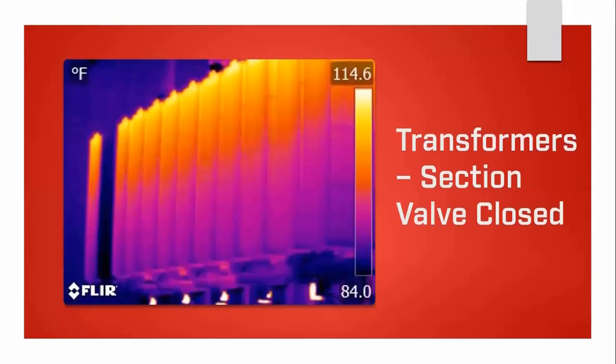And we've seen a similar image to this: transformer section valve closed. This one is the easiest to interpret. The section valve was not opened after transformer service. So we can see that black line going down towards the left-hand side of the image.